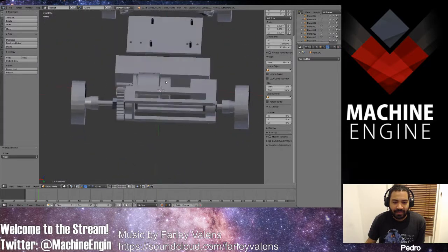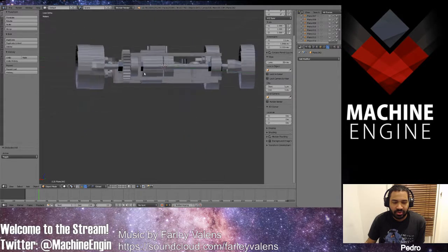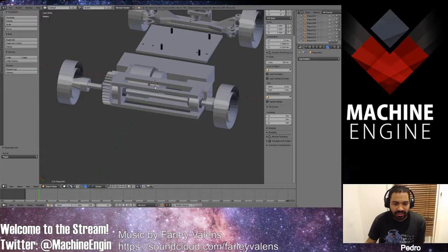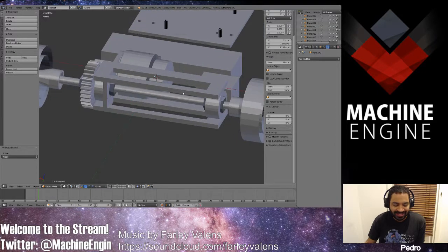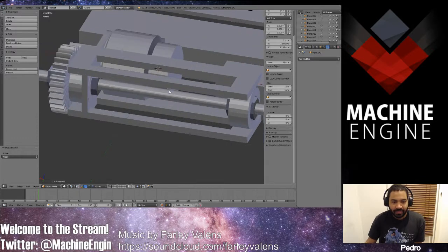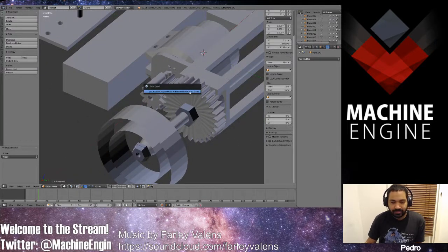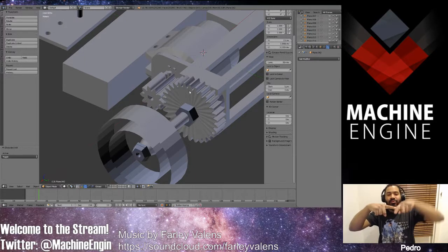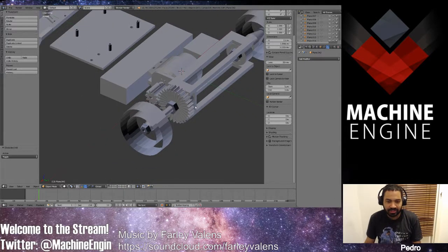and redesigned the way the motor attaches to make it more robust, make it harder. This part is way stiffer. It's sturdier, stiffer. So it's gonna hopefully perform way better, because right now the current design has a lot of wobble in it. It jitters a lot because it's a really long bar on a thin thing, and it moves like that constantly. It's crazy. So hoping this will fix it.